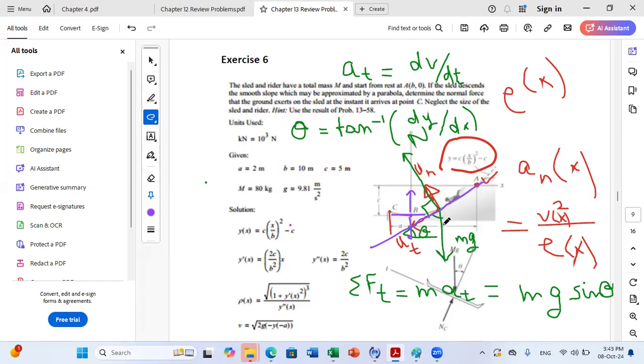But in other cases, like the Formula 1 problem, it's completely different. And you should consider the contact line. When you know where your contact line is, normal is perpendicular to the contact line. Here, the contact line is tangent to the path. That's why normal is along un. While, for example, in the Formula 1 problem, the contact line was not along the tangent to the path, if you remember. At that time the normal had two components, one along un, one along ub. Okay, Doctor, thank you. Okay.